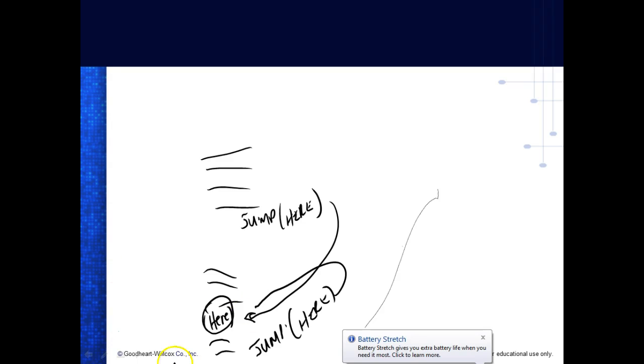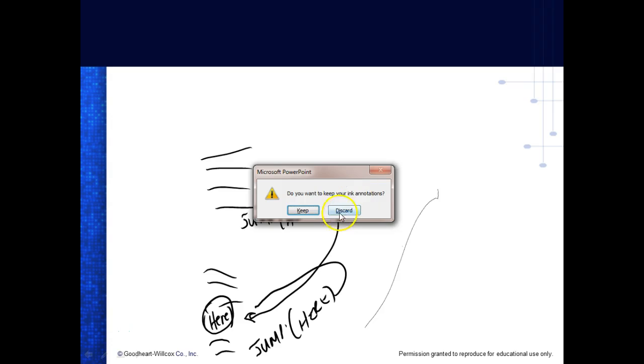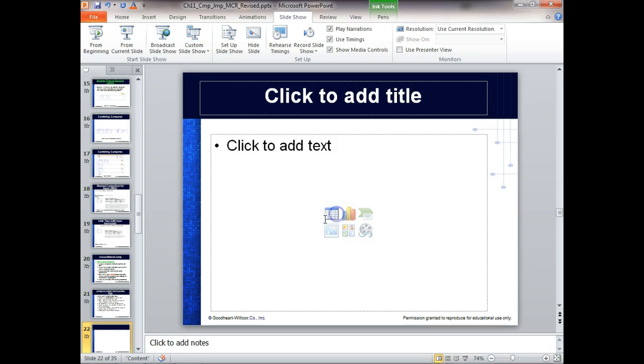So when we come up here and look at our project tree, anytime you create a new project, it automatically inserts a program file called what? Ladder 2. And this is true in Siemens too, they call it OB1, because it's a program block, is what they call it.